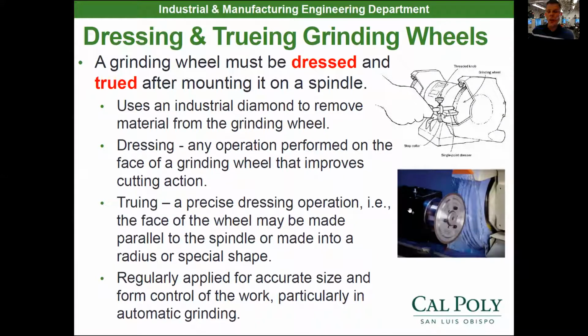So if you've been to Kevin's welding lab, he never does that. If you look at some of those, because he sharpens his tungstens on them, it makes a big V or groove in the wheel, which is dangerous, actually. I keep telling him that. So you need to always dress your wheel and don't want to ever get a big V or groove in the wheel like I see in the welding labs a lot of the times. You got to go back in there and true those things up, or else you're going to end up having a chunk come out of that wheel.